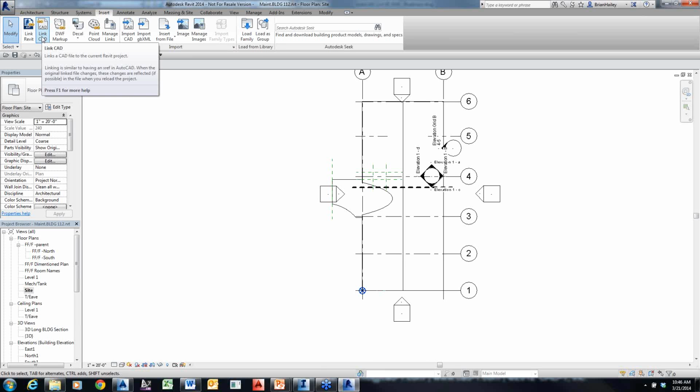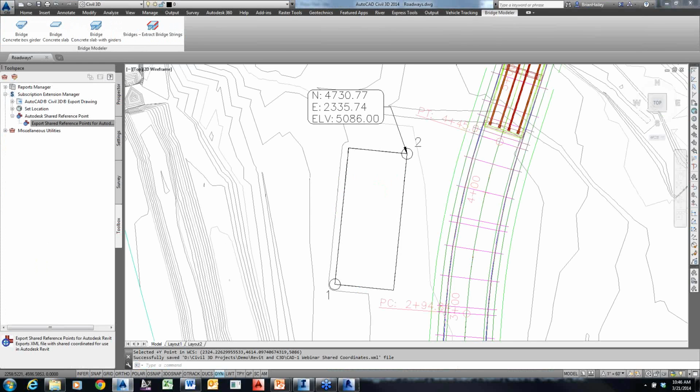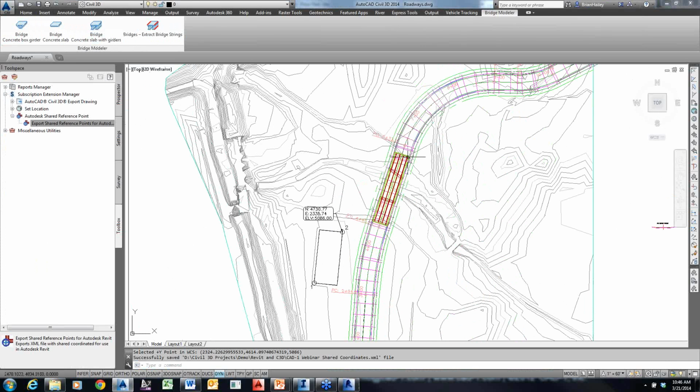Now, if you get into an area where your Revit topo surface is drastically different than your civil surface, what you can do is go in and add additional data to the Civil 3D surface. So basically, and let's do this real quick, just go create points on a grid in this area. This is the area that I need the additional detail on. Get the elevation from the surface, and then add them to the surface. And then export that out.